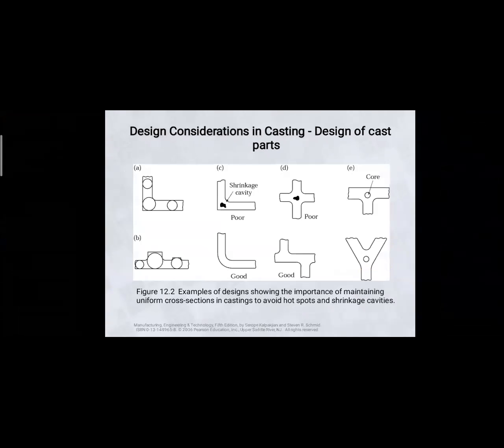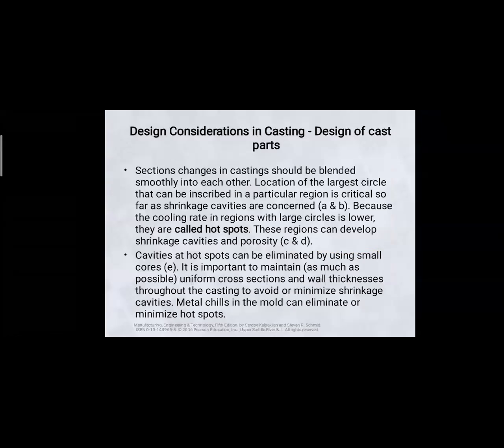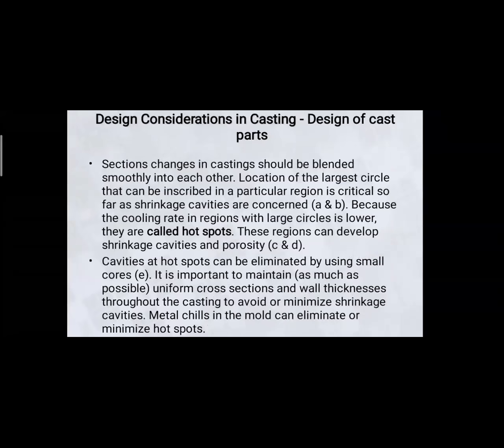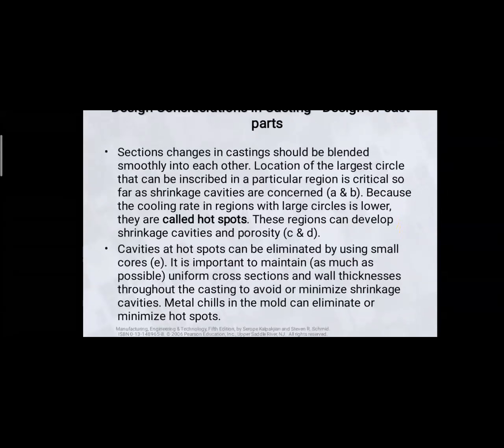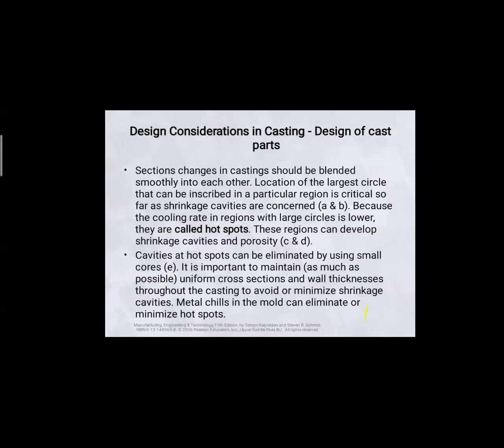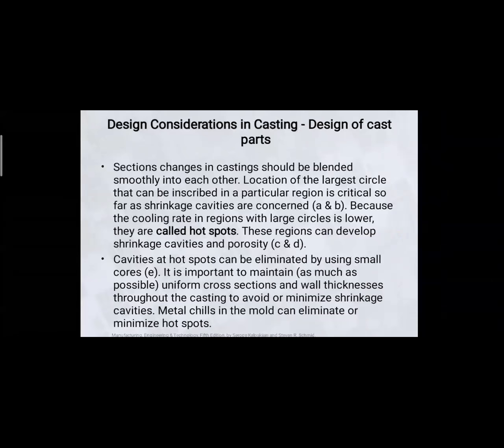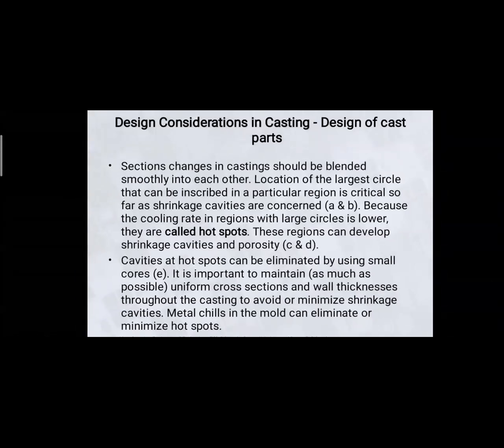Okay, so for this type of diagram, they are explaining in this slide. It explains the design considerations in the casting, the design of the cast parts. The first point explains that the section changes in the casting should be blended smoothly into each other. The location of the largest circle that can be inscribed in a particular region is critical so far as the shrinkage